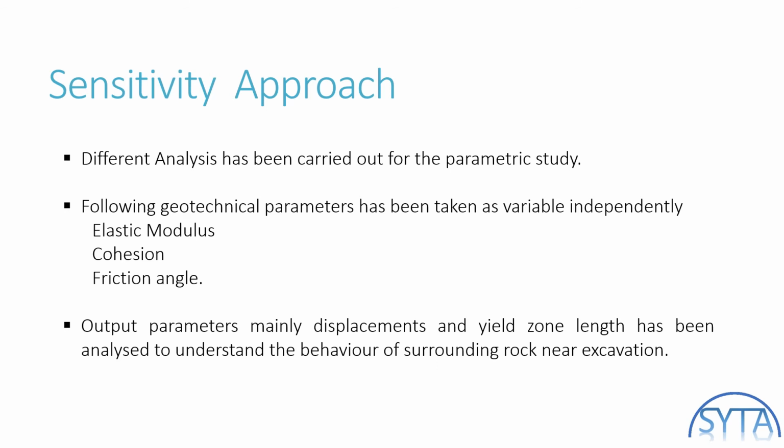So out of the several input parameters, we have taken basically three variables, like elastic modulus, cohesion, and friction angle. And the output parameters are mainly displacements and yielding zones. Those are being analyzed to understand the behavior of the surrounding rock near the excavation.